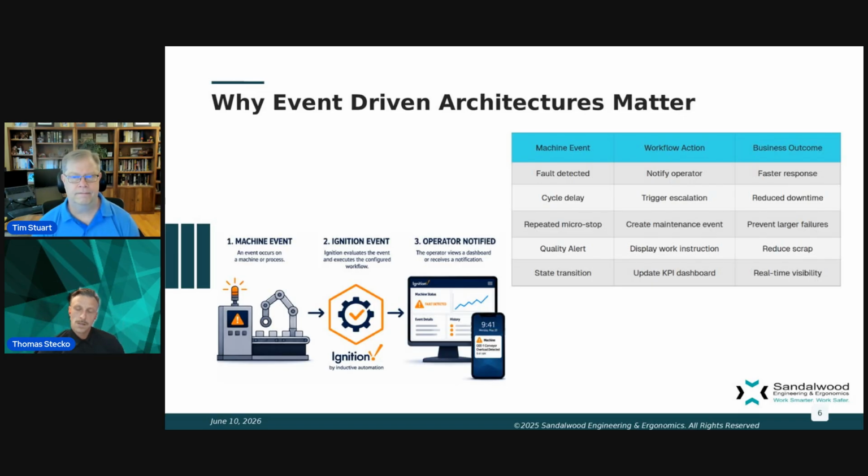The approach looks at, let's say we get a machine fault. Let's say we get a code of 996, which means e-stop latch X. But if we have those 100 machines that we discussed earlier that are all the same, they should have the same fault codes, the same warnings, the same type of dictionary. It's like, aha, we can create a UDT for faults based off of the code. 776 might be a specific code. And now we can do something with that specific data.